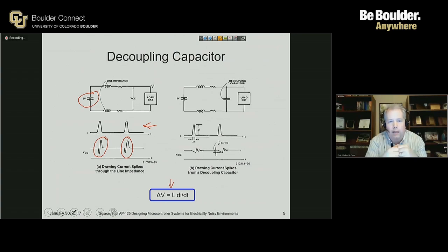So our job as hardware designers at this point is to make sure that we understand what the manufacturer of the silicon specifies as a requirement, and that it is met in our design. If we cannot do that, then we're not delivering a robust hardware platform that you can rely on as a product. So first step, understand what the requirement is. Second step, make sure that we meet the requirement in how we design our circuitry.